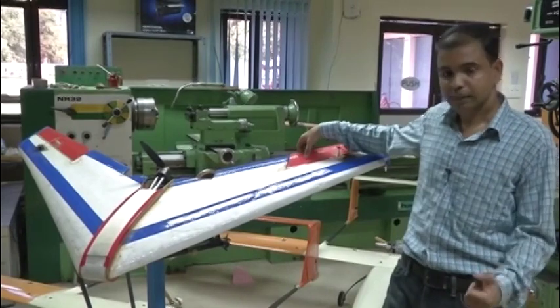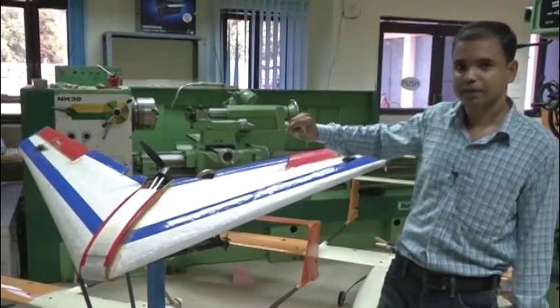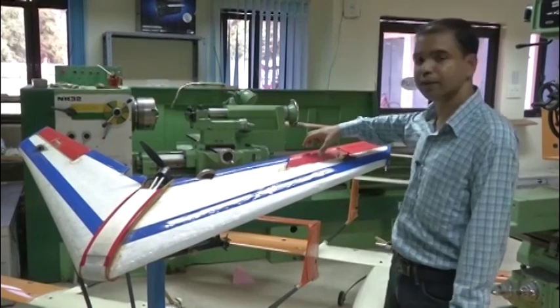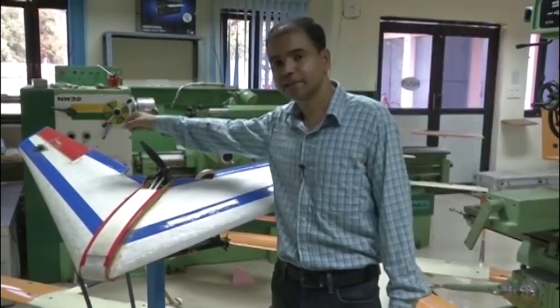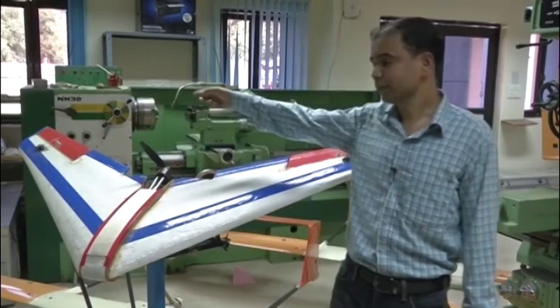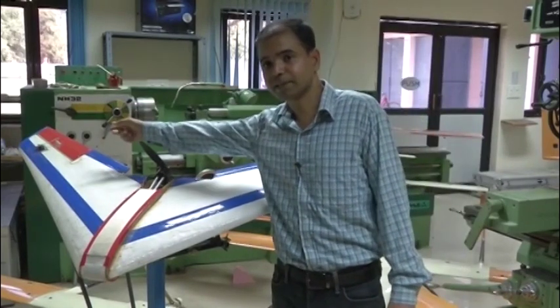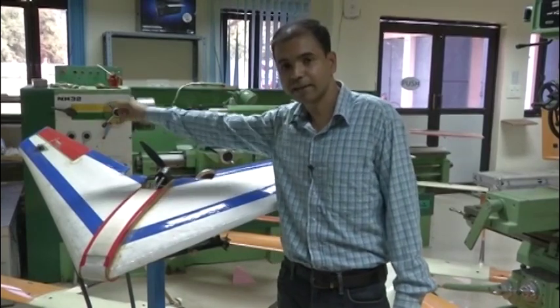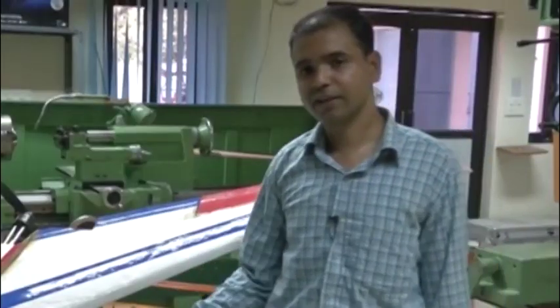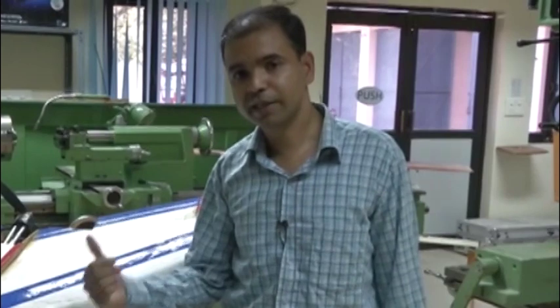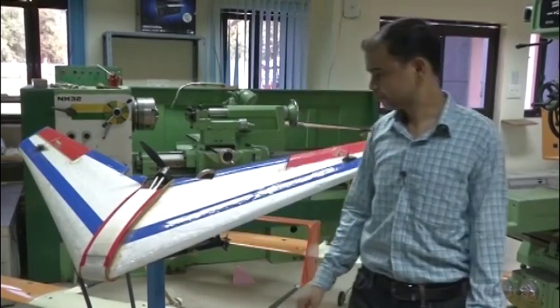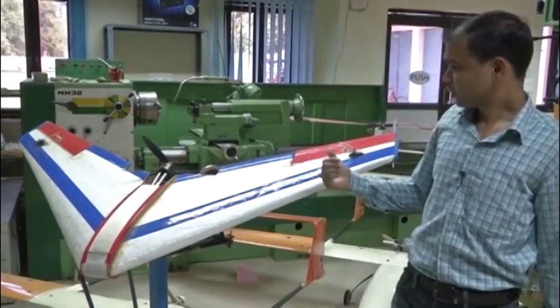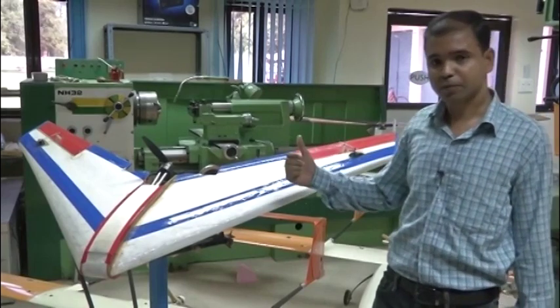I will give symmetrical deflection for the climb, and because I am taking a right turn, I will reduce left aileron deflection and I will increase the right aileron deflection. So what happens? The right aileron deflection will become very high, and that will enter into non-linear region. Designing of control becomes complicated because we need to handle the non-linearity which has arisen because of the deflection entering into the non-linear region.